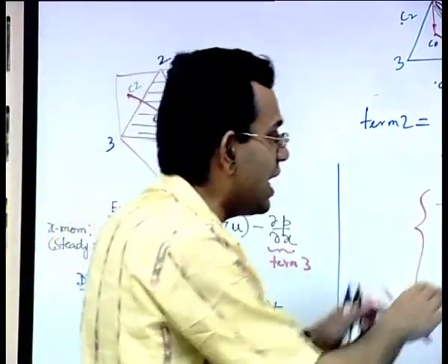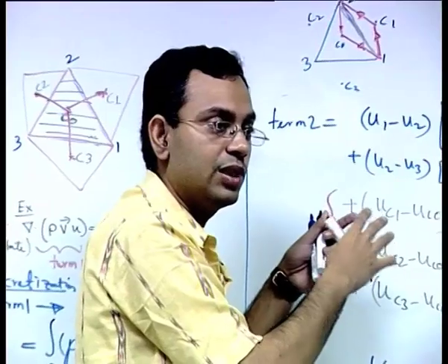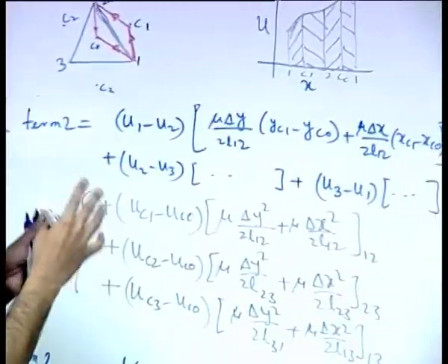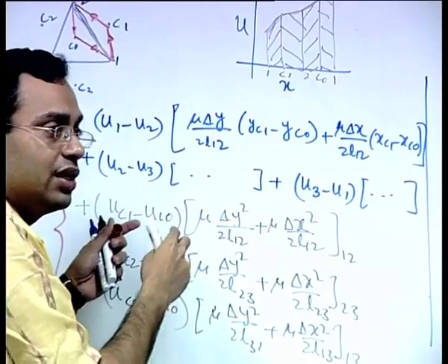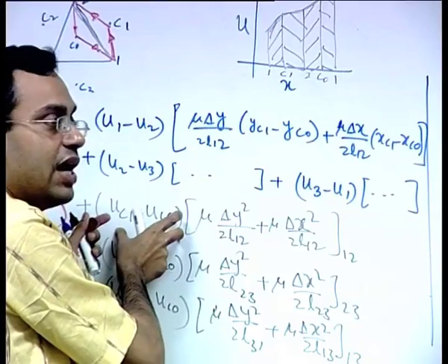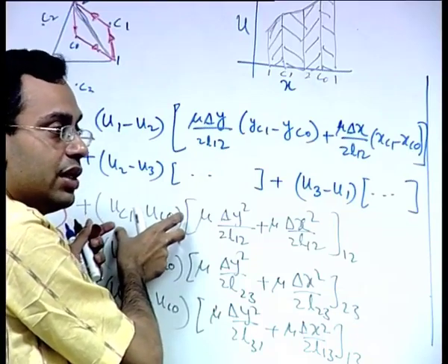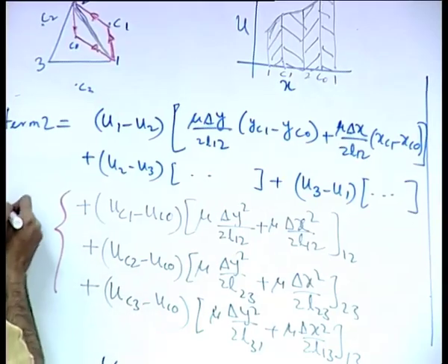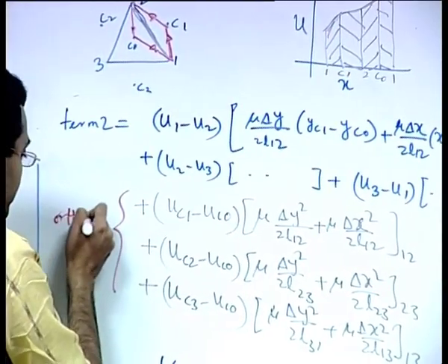So this is just like the structured grid formulation, equivalent, not exact but conceptual equivalent, where the diffusion flux is proportional to the difference in the values of the neighboring grid points. So this we call as orthogonal diffusion flux.